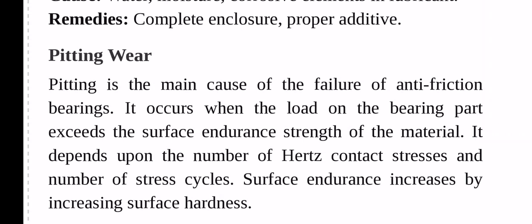Pitting is the main cause of the failure of anti-friction bearings. It occurs when the load on the bearing part exceeds the surface endurance strength of the material. It depends upon the Hertz contact stresses and the number of stress cycles. So surface endurance increases by increasing surface hardness.